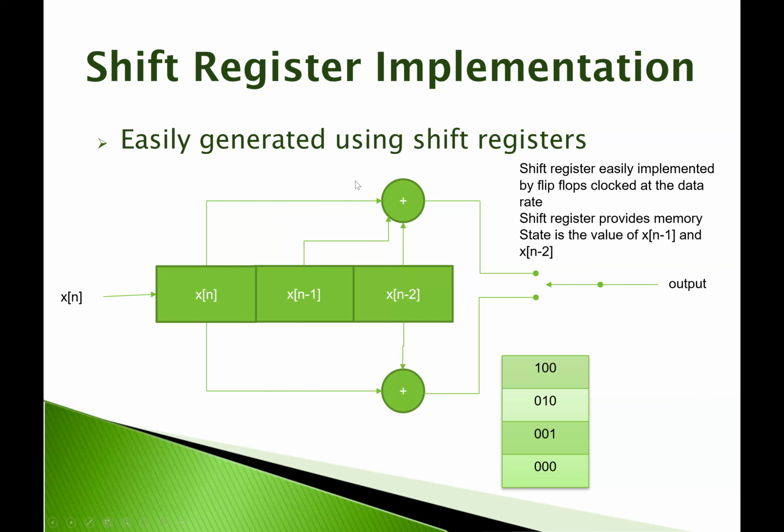So this is the modulo 2 operation, where we have this 1, 1, 1 type operation, right? So these are weighted by just a 1 value. Okay, so that's generator G0. This would be generator G1. And here we have a 1, 0, 1 type of operation.